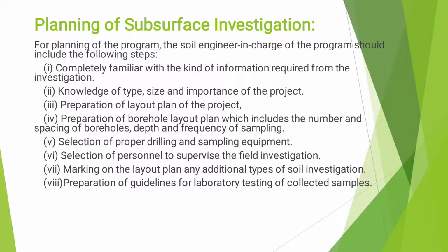Next, planning of subsurface investigation. Planning is an important factor. As a soil engineer in charge of any program, he should have knowledge of the following steps, and should be completely familiar with the kind of information required for investigation, such as the type, size and importance of the project, preparation of layout, preparation of boreholes, selection of boring, drilling and sampling equipment handling, selection of personnel to supervise the field investigation, and preparation of guidelines for laboratory testing of collected samples.